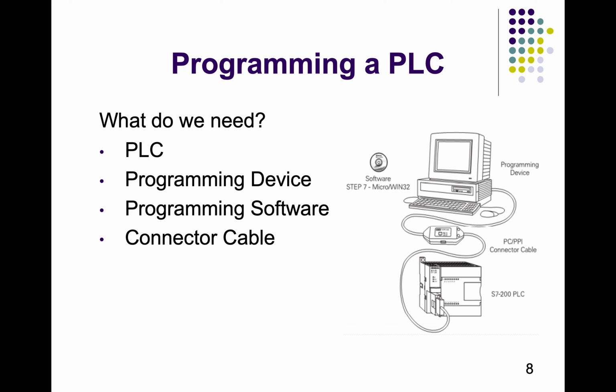Programming a PLC. What do we need to program a PLC? Of course, we need a PLC, which can be a fixed PLC or a modular PLC. Then we need a programming device. This can be a computer or some handheld device. Then we need programming software. Then we need connector cables that connect inputs to the PLC or outputs to the PLC. Then some cables to connect between the computer or programming device and the PLC.